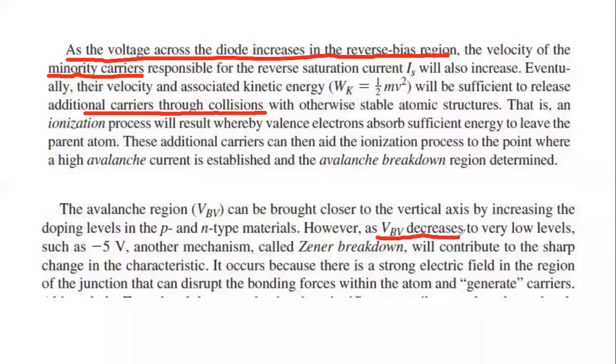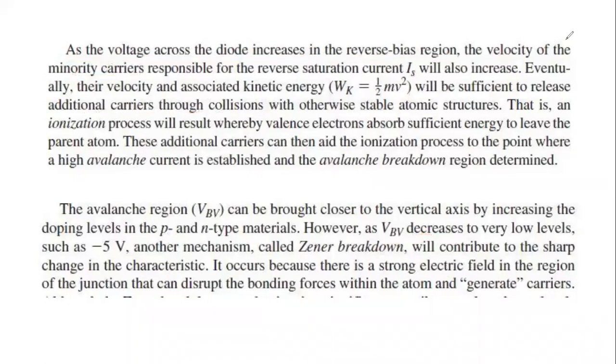So this is the slide for those who don't understand how this Zener region is created. I'm again telling that the Zener region is basically created by minority carriers. We know that they are minor, but when we apply so much energy, so much potential, after some time it gains the energy, it gains velocity, and it starts to move. So it collides with other atoms, and from other atoms it releases electron hole pairs. When it releases, the electron flow starts in huge amount. So that is the Zener region, and the operation of Zener diode happens. I think everyone is clear how the Zener diode is created.